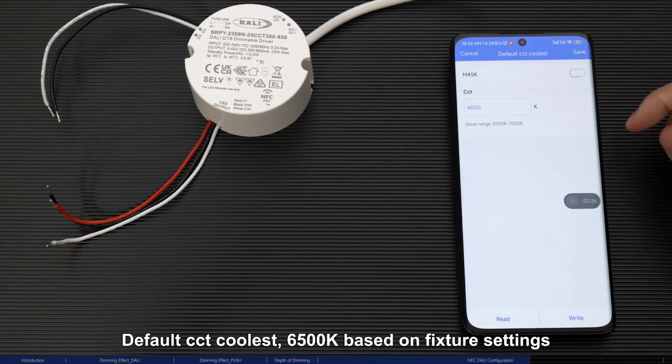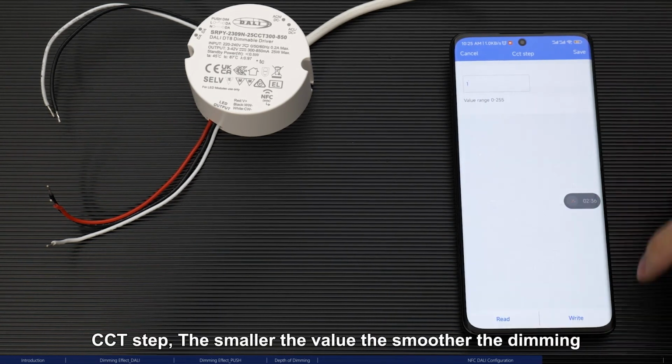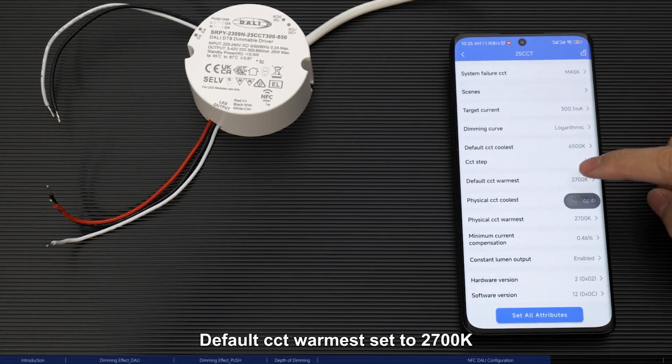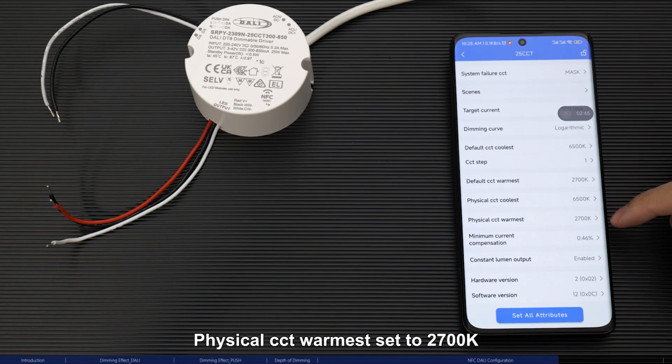Default CCT coolest, 6500K, based on fixture settings. CCT step, the smaller the value the smoother the dimming. Default CCT warmest set to 2700K. Physical CCT coolest set to 6500K. Physical CCT warmest set to 2700K.